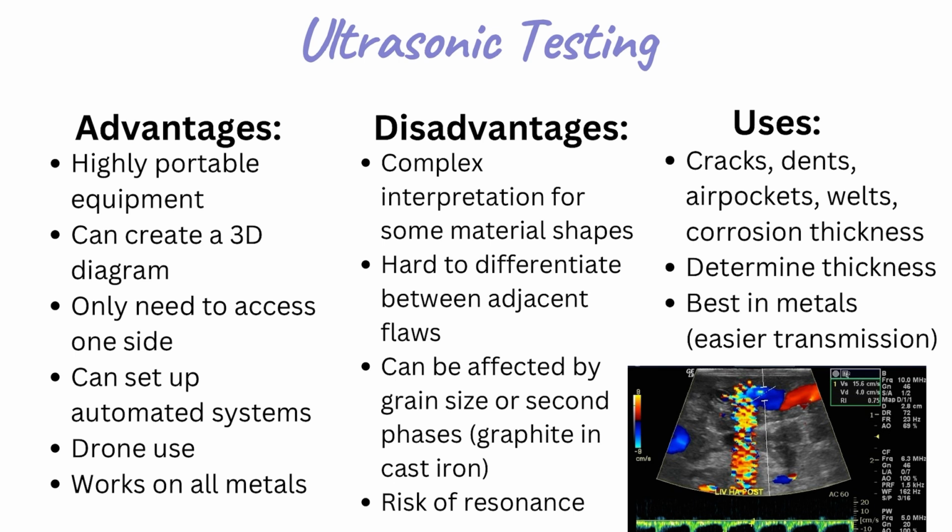Some uses of ultrasonic testing is to test cracks, dents, air pockets, welds, corrosion, thickness in a material. It can also be used to determine the thickness of a material, and it is also best in metals, as metals have an easier time transmitting these sound waves.